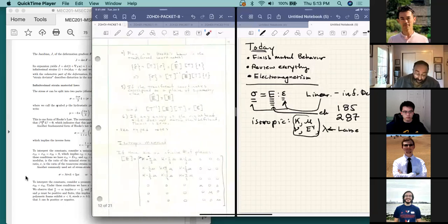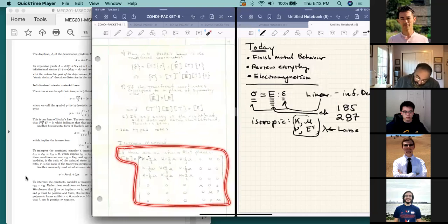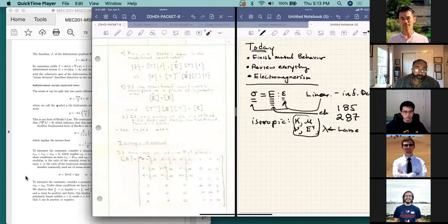The elasticity tensor, as we know here, and I'm not going to rewrite it because we're already just going through a review, has just simply two entries here that can replicate every single one of the parameters inside the elasticity tensor. So normally each one of these things is labeled E1111, E1122, etc. And it turns out that each of those parameters can be represented as some combination of mu and kappa. In this case, on the diagonal, it's kappa plus 4/3 mu, and then off diagonal is kappa minus 2/3 mu, and then over here, mu, mu, mu.